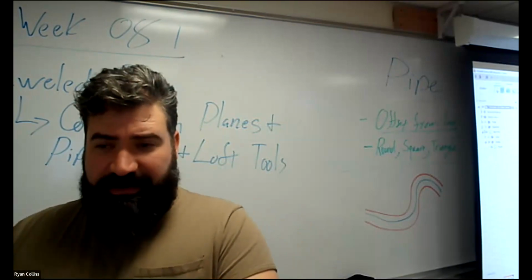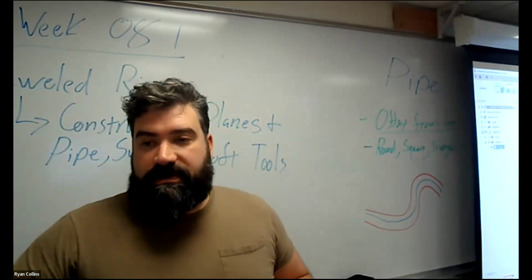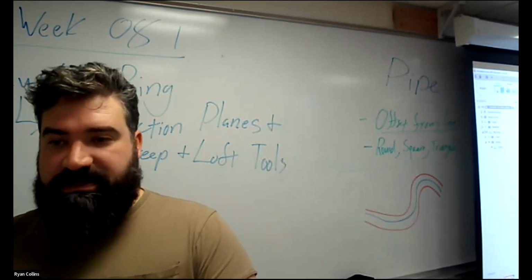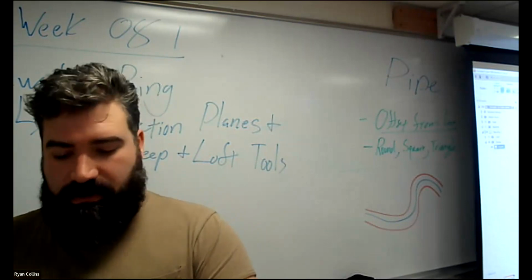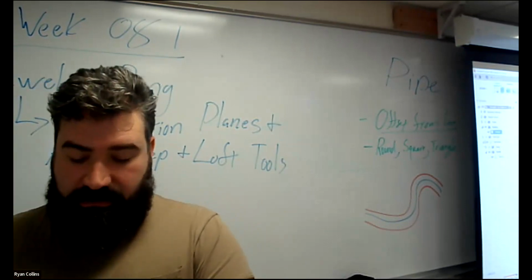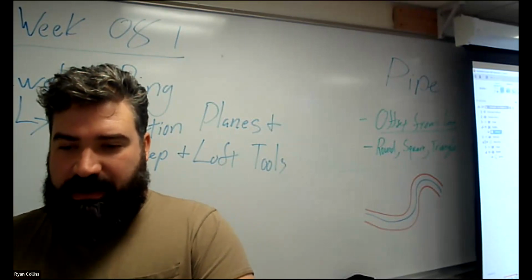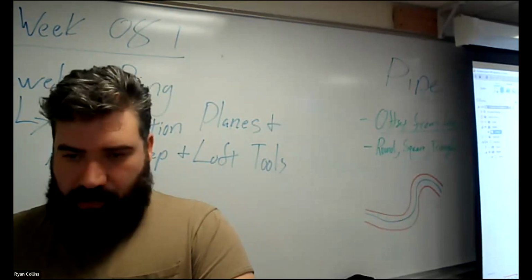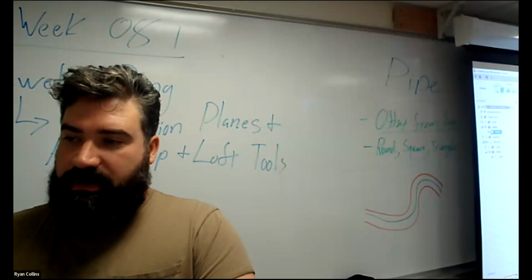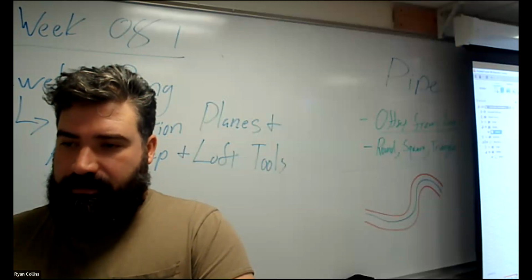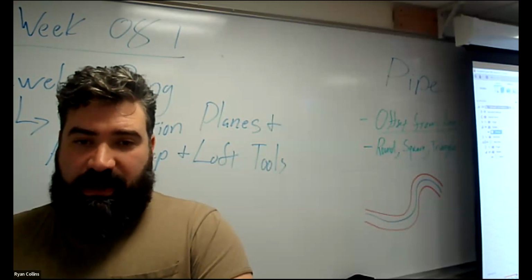Okay. So I've got that one ring. Well, I said you can't make just a simple ring, but we can play with this. So take this single one. Let's copy and paste, make a new one. There we go. Oh, helps if I hit Control V. Now the problem is it plopped my center rotation way off. So what I want to do is set my pivot point right in the center. So go over to the move copy, pivot point right in the center, deselect, there we go. Now this is already a copy, so we're good.